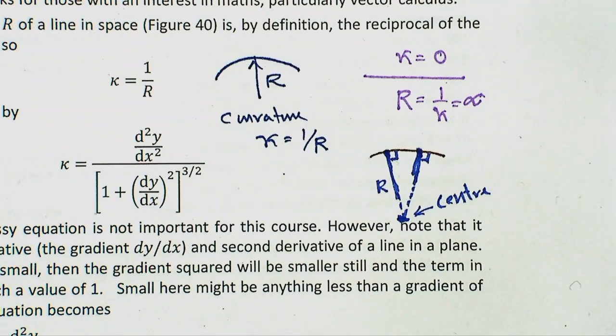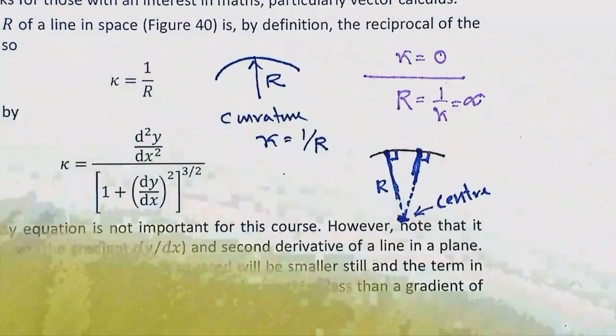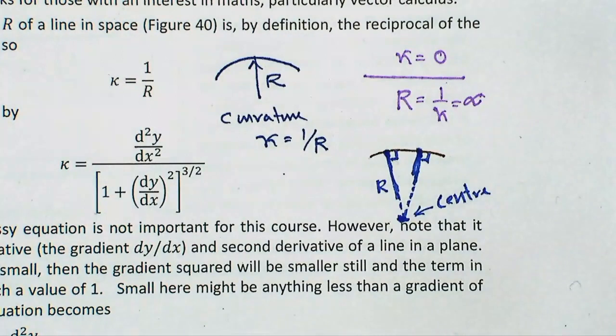Now forget about this second bit here for the time being, because that relates to the stress. Consider the first and the last one. M over I is equal to E over r. So if you know moment that you are applying at one cross section or bending moment there, then you could get, so there is a relationship between moment and curvature. So 1 over r is curvature in this case. So you apply more moment, it will curve to a higher curvature.